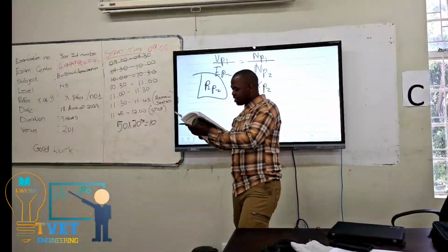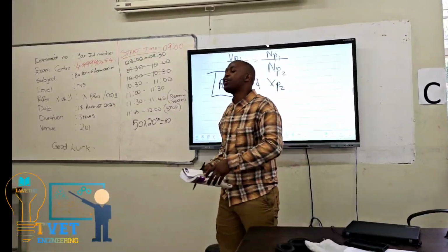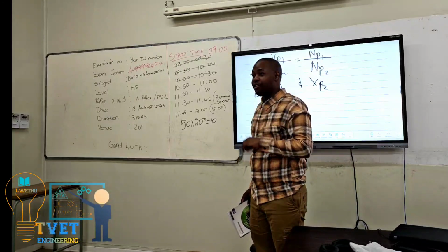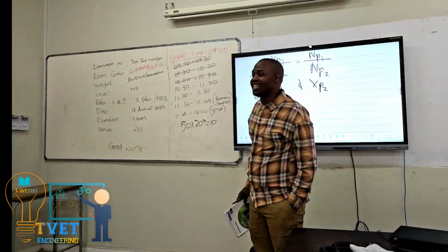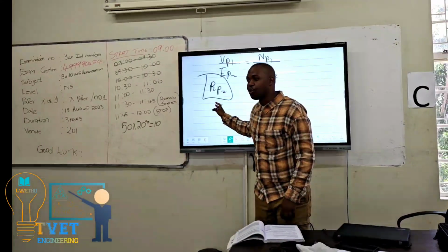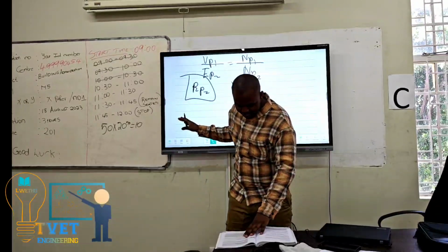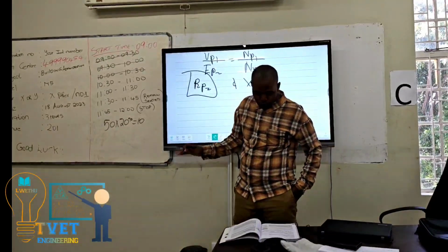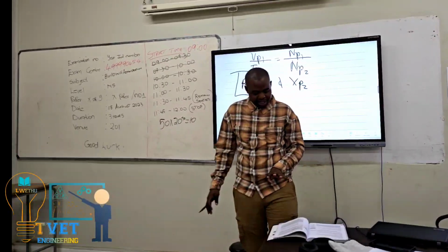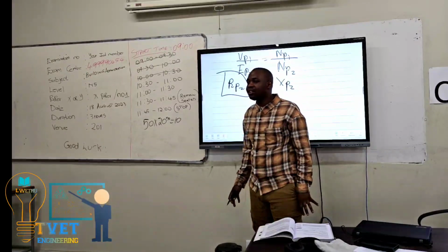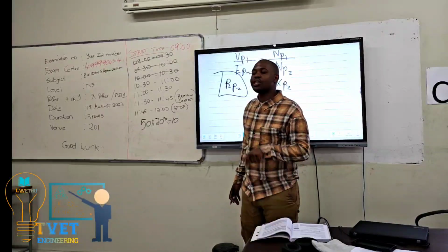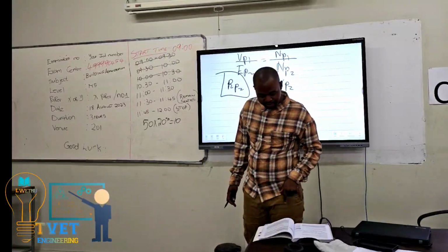These standstill values have to be converted to rotating values. How do we convert them? Simply multiply all frequency-dependent quantities by the slip.